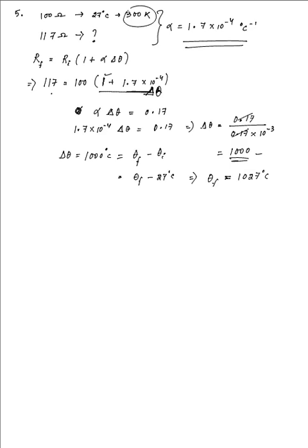Okay, now moving over to the next bit of question. If a negligible amount of current is flowing through a wire of length 15 meters, having an area of cross section equal to 6 times 10 to the power minus 7 meters squared, and its resistance is obtained to be equal to just 5 ohms, then we need to calculate the resistivity. Now, as you know, the resistance R is equal to rho L by A. So from that you have to find the value of rho, that is equal to RA divided by L.